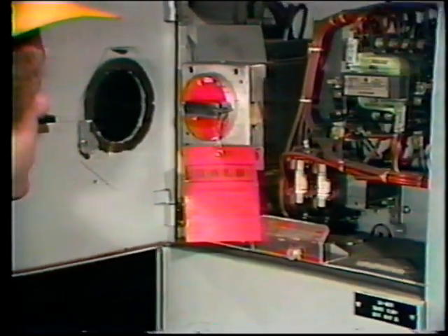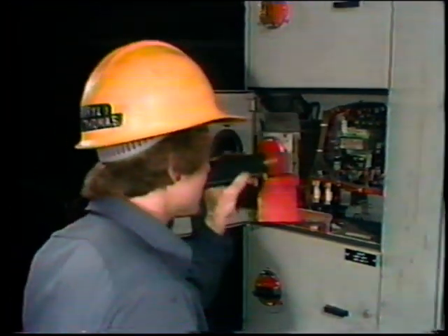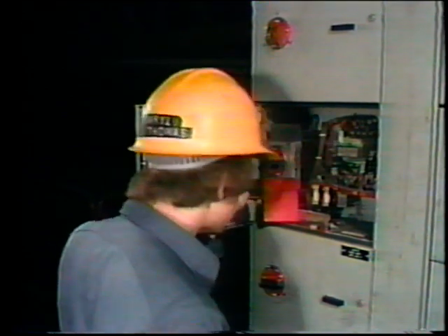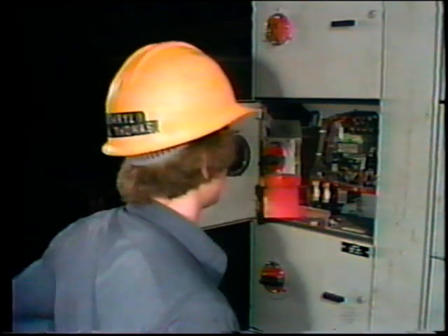Once you've narrowed down the possibilities, the fourth step is to inspect the controller. This step includes a visual inspection of the controller and any necessary measurements to locate the cause of the controller's malfunction. But in order to inspect a controller, you're going to need a guide to where its components are physically located. Now, the controller's schematic only shows the electrical connections of the controller's components, not necessarily their physical location. To physically locate a controller's parts, you need to use a wiring diagram.